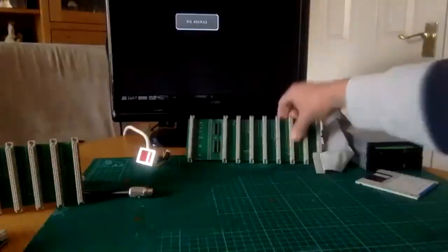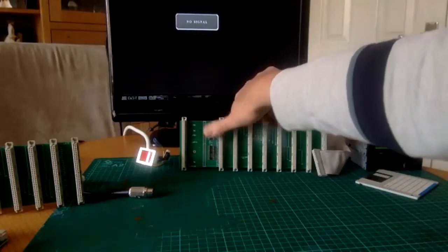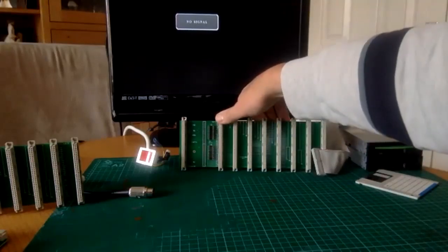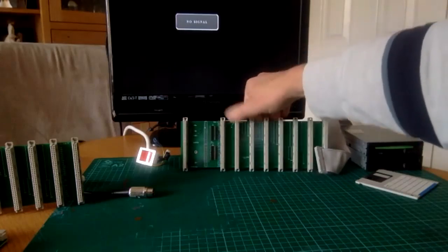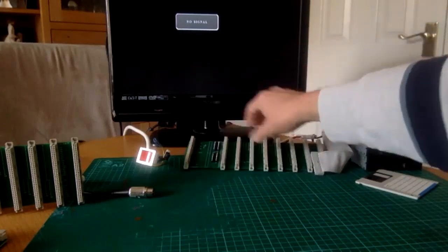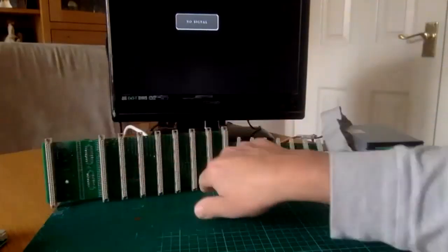Yeah, so I think that's pretty much it. There's not much left then to dig into apart from the backplane itself, where you've got your buffered CPU slot, if you populate the buffers, to drive more cards. I was running it in unbuffered mode for that one, but the new board is actually buffered on the CPU card, so it should be able to drive more cards out of the box, being the next gen. Did that answer the question?